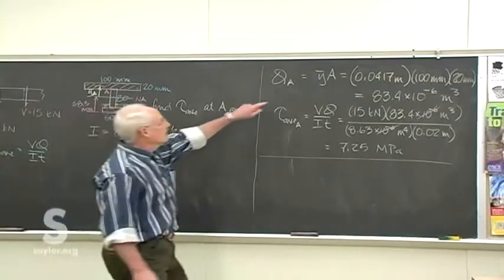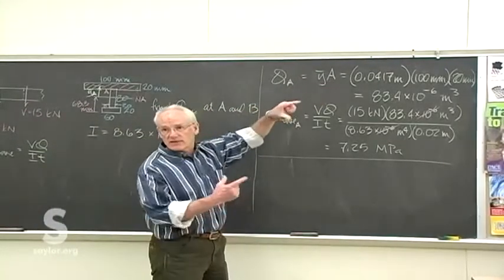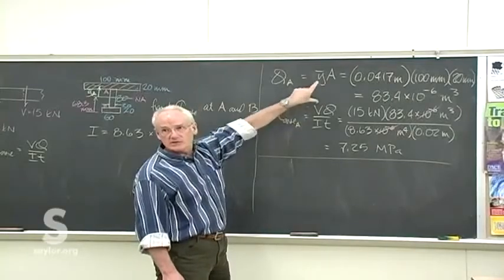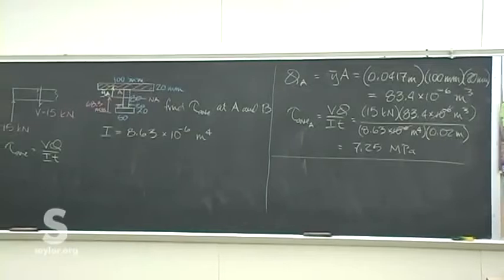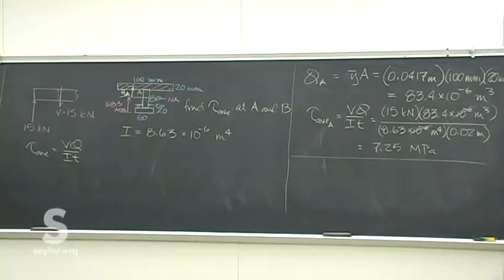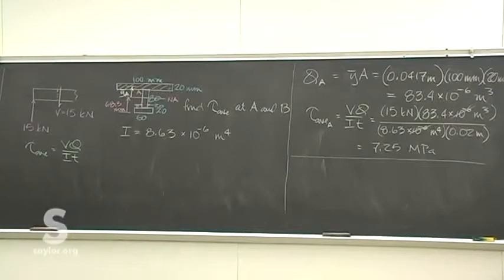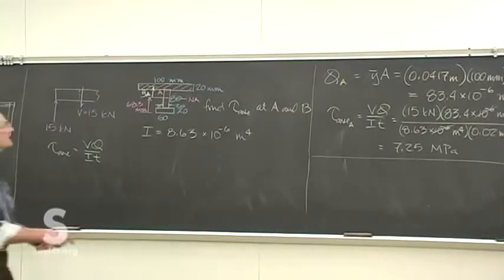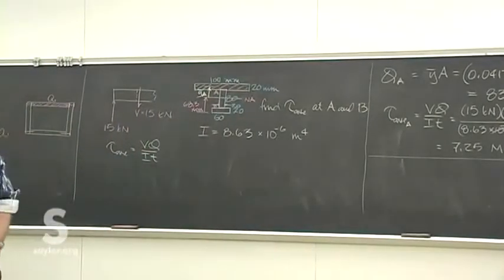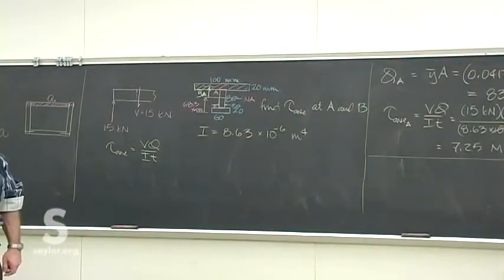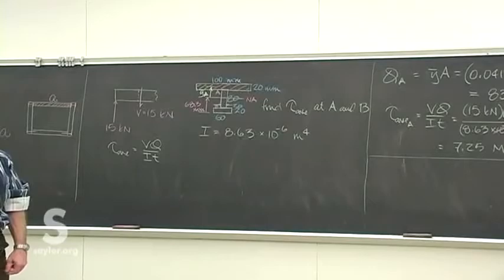That's where a whole bunch of things get very much easier, and a bunch of B's cancel, a bunch of H's cancel. The book lays that out, but that's a rectangular beam only, and we're not working with one of those here. It does not apply to a rectangular portion thereof. The entire beam has to be rectangular to use that 3V over 2A.